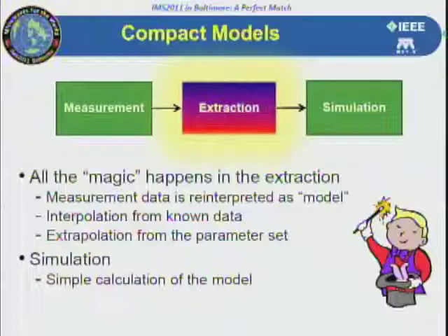And each one of these steps potentially is going to add additional risk to our ability to use this model in a design type situation. So we already talked very briefly about the fact that measurement in general is going to add measurement uncertainty. I'm assuming that whoever's taking the measurements for us does a good job of calibration and knows how to take the measurements in general, but certainly measurement uncertainty, whether it's systematic or random, is going to introduce error into our system.